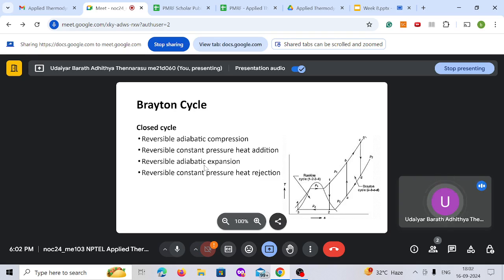That was the idea of putting a Carnot cycle inside the two-phase region and converting it to a Rankine cycle. And then we said the practical difficulties of operating in a two-phase region, and then we tried to take the process out of the two-phase zone.